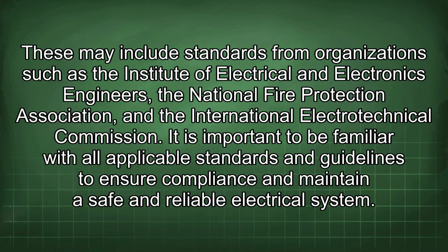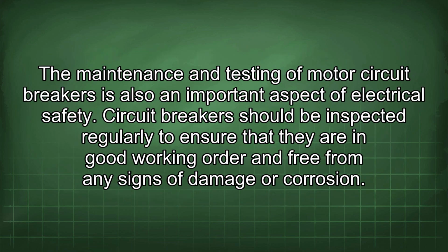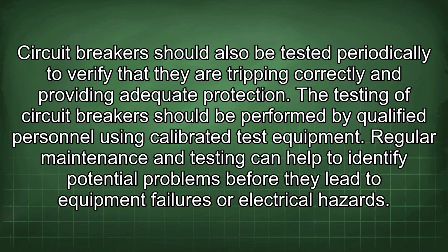reliable electrical system. The maintenance and testing of motor circuit breakers is also an important aspect of electrical safety. Circuit breakers should be inspected regularly to ensure that they are in good working order and free from any signs of damage or corrosion. Circuit breakers should also be tested periodically to verify that they are tripping correctly and providing adequate protection. The testing of circuit breakers should be performed by qualified personnel using calibrated test equipment. Regular maintenance and testing can help to identify potential problems before they lead to equipment failures or electrical hazards.